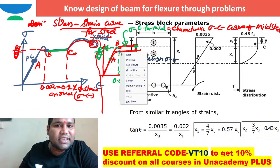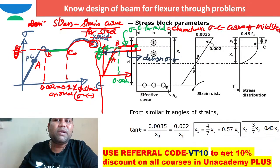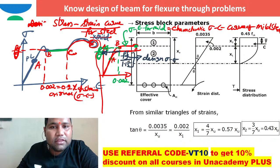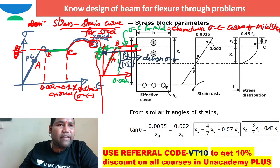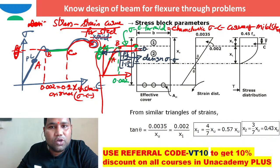The characteristic strength is Fy. Fy divided by what is the factor of safety for steel? What is the factor of safety for steel in the limit state of collapse? In the limit state of collapse, the factor of safety for steel is 1.15. So I can directly write this stress here as Fy by 1.15. That 1.15 is the factor of safety for steel in the limit state of collapse, and definitely this is equal to 0.87 Fy, right?